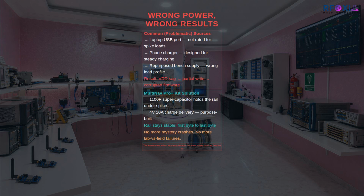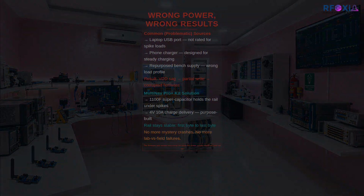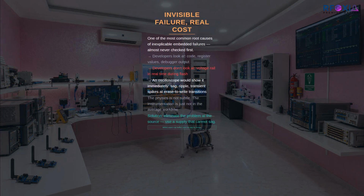This is not a hypothetical failure mode. This is one of the most common root causes of inexplicable embedded development problems, and it is almost never the first thing anyone checks. The reason it is hard to diagnose is that the failure is invisible at the level most developers operate. You are looking at code, you are looking at register values in the debugger. You are not looking at the voltage rail in real time with an oscilloscope during the flash operation. If you were, you would see it immediately, a sag, a ripple, a transient spike when the flash controller transitions between erase and write states. The physics is not subtle. The instrumentation required to see it is just not part of the average debugging workflow.